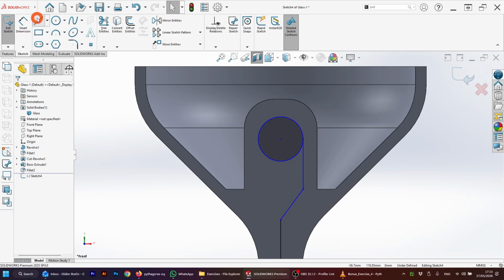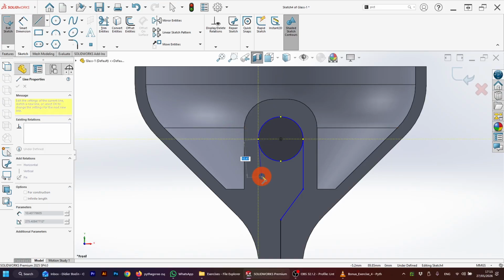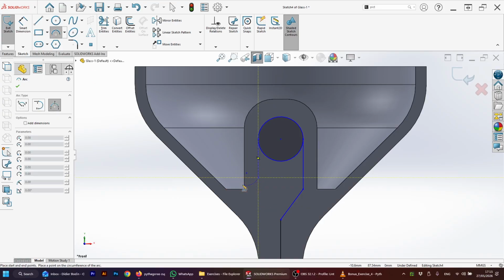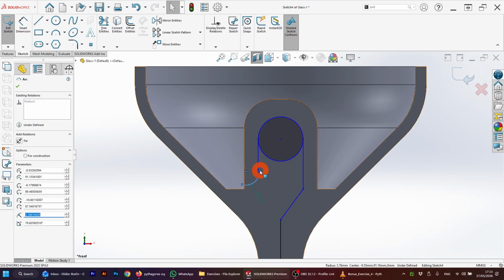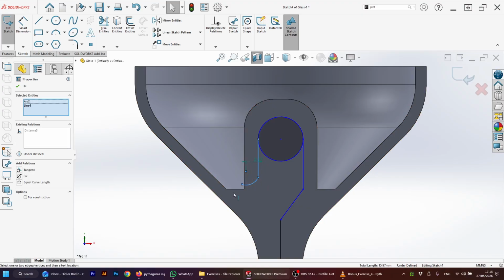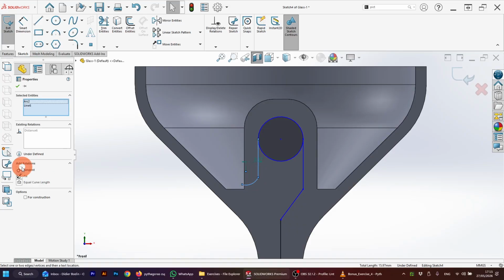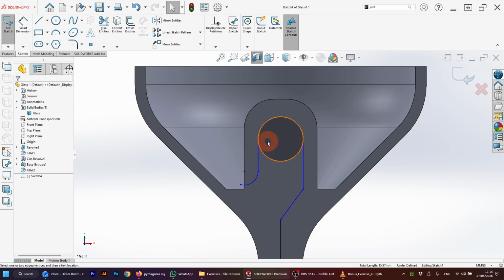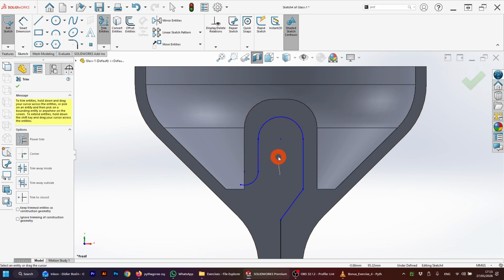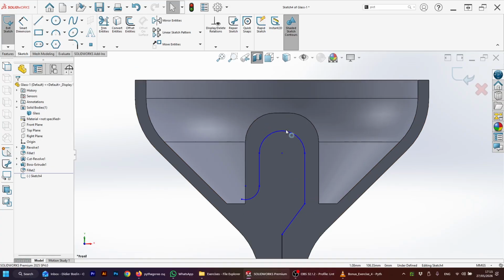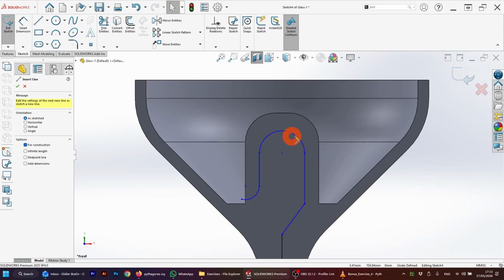And okay, let's put a line before, from the edge until here, and then from here to here. Select the two lines, first line, Control pressed on the keyboard, second line, and on the left, tangent. Here I'm going to use trim to remove this. So now we can see that our pipe is going to travel like this. If I want to control exactly how much plastic there is between this and that, I can put a center line